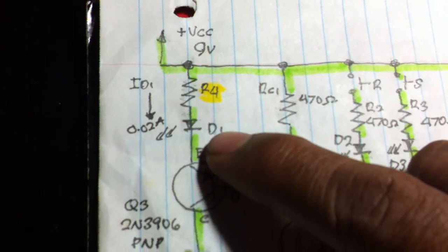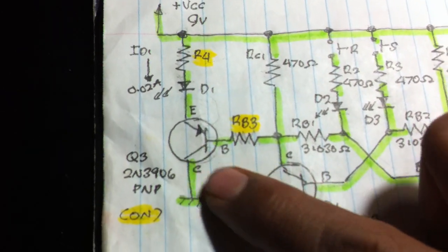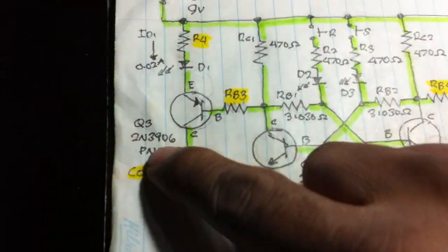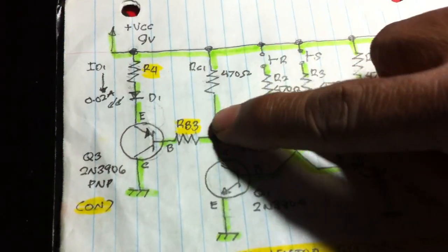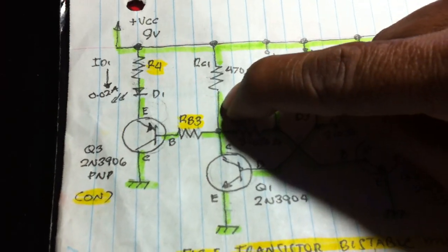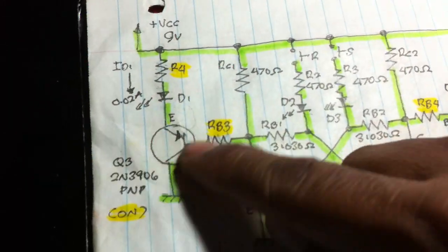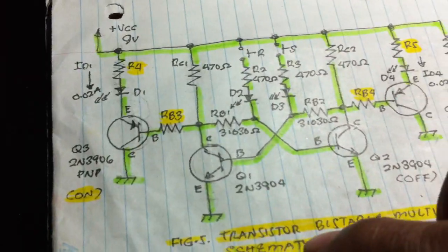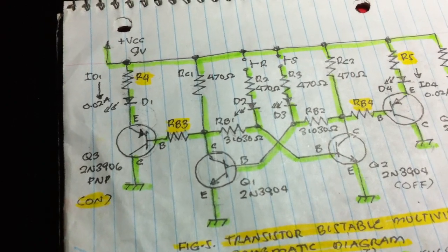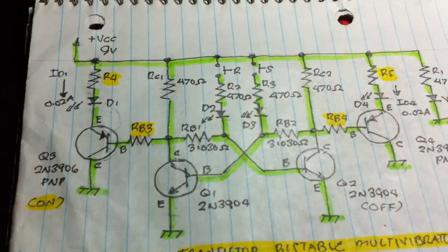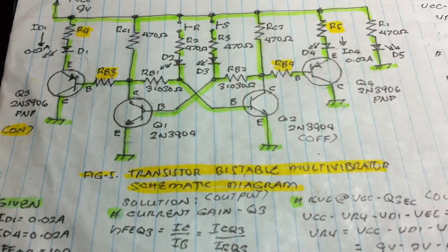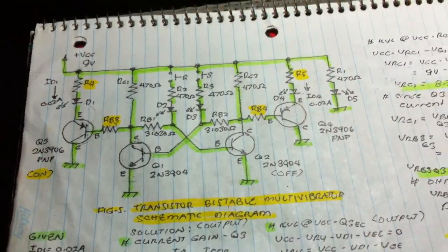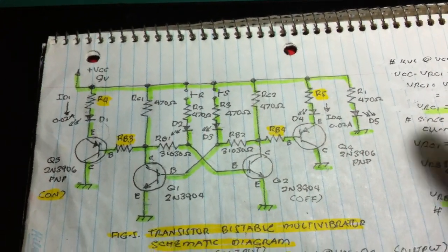Now the LED is in here with the PNP using 2N3906, which is the complement to the 2N3904. Before, we put the LED in here. Now it's here, providing a constant current source to the LED. And now the transistor transconductance developed will no longer appear. Because of that, we're going to compute the values of the resistor from our new circuit. And this is now our new circuit using the PNP as a constant current source.